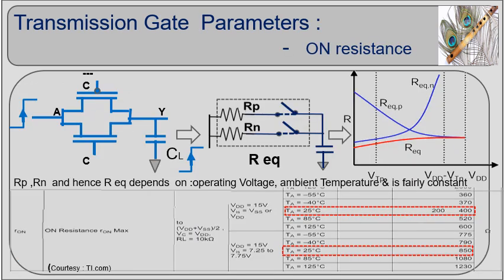The parallel, complementary conducting transistors offer fairly constant resistance. The decreased transistor resistance will increase the switching speed and reduce the propagation delay. Further advantages of reduced resistance are faster signal propagation, improved signal integrity, reduced power dissipation, bidirectional symmetrical conduction, reduced noise sensitivity, wide voltage range operation, etc. Due to the bidirectional symmetrical conduction property, a transmission gate is used in both analog and digital applications.